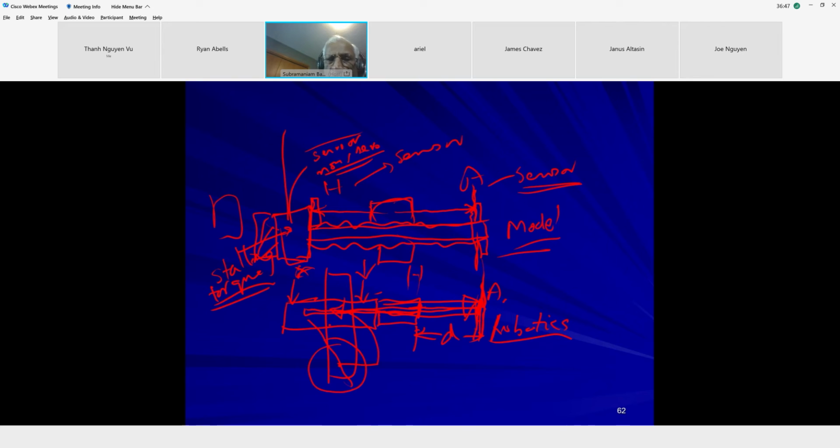Okay, so what are you gaining? If it is a screw, it will maintain its position. If it is a cylinder, it may not maintain the position. But this sensor, when coupled to the PLC, will cut the power off and save the motor from getting damaged. Same way, the home sensor will bring it back all the way until the home sensor becomes true.